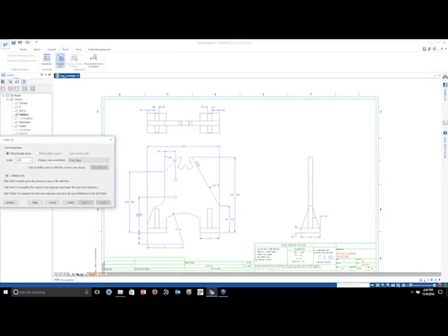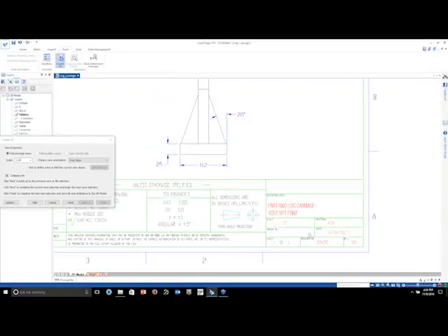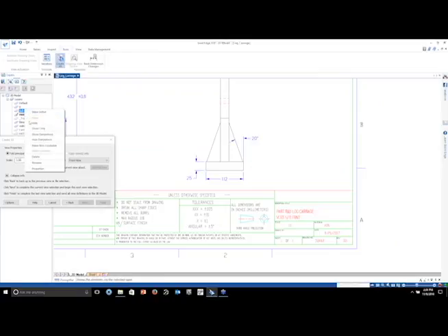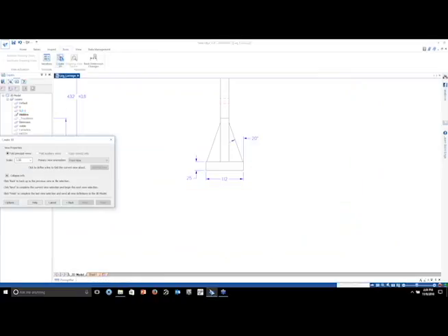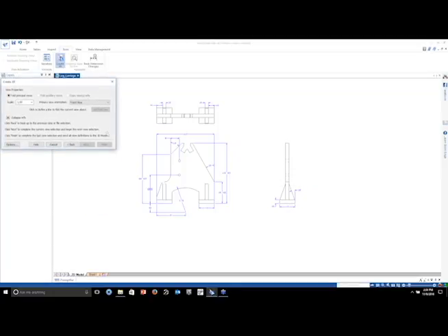All right, so now let's grab my geometry. It's going to ask for my front view, so I'm going to define this as my front view by clicking and holding a fence around it. It gets all of my dimensions, like everything I want. This says good. Say next. Let's get my top view. I can set a fold line, but in this scenario, I'm not going to use it. I'm going to do it on the side view to set my fold line. I'm going to show you something once we get to the part file, how to manipulate it. So I'm just going to go ahead and skip the set fold line, say next, grab my next.